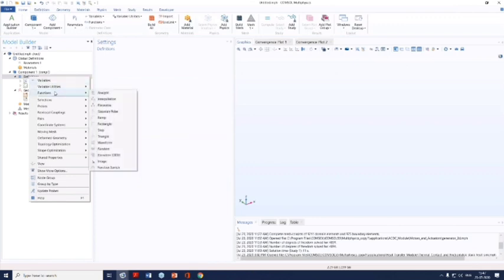The functions can be used in order to provide any excitation to your structure, or if you have some functional dependence in your material properties. Just for an example, the thermal conductivity is a function of some temperature data, or the electrical conductivity is a function of the temperature data which you have obtained from your experiment, and that lookup table if you want to import in COMSOL, in that case the interpolation function can be used.